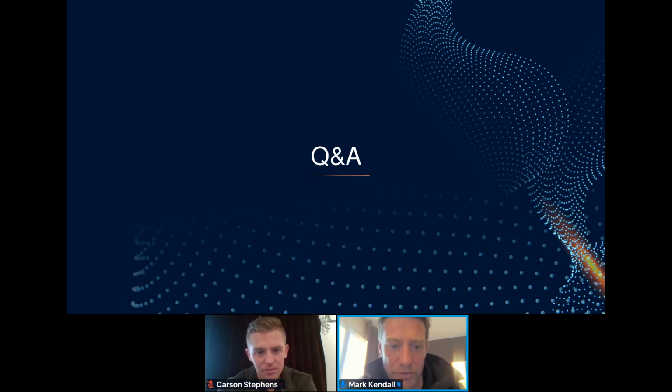So we've performed numerous tests over and over again. We've not tripped other modules. We've not reignited after the event. I was working yesterday and using water to do a comparison test, which had a massive shorting effect within the battery itself. So that is one of the key points of Fike Blue. It is a lot less conductive. We don't see the shorting in the other modules that we do with other fluids.